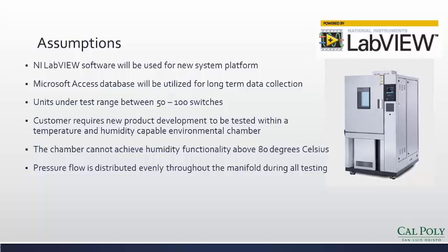Before beginning to work on a solution for this problem, a few assumptions need to be made. First being that NI LabVIEW software will be utilized for the new system platform, and a Microsoft Access database will be used for long-term data collection. Following that, we plan to test between 50 and 100 switches. Next, the customer requires new product development to be tested within a temperature and humidity-capable environmental chamber, such as the one on the right. Following that, the chamber cannot achieve humidity functionality above 80 degrees Celsius due to the wick drying out. And lastly, pressure flow is distributed evenly throughout the manifold during all testing. This will make sense a little more down the road.